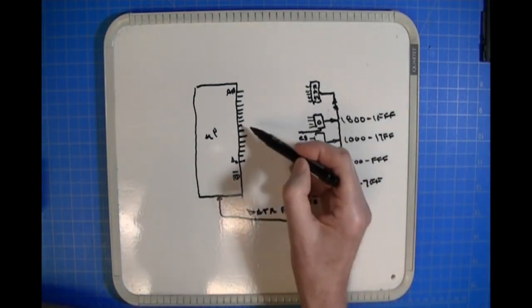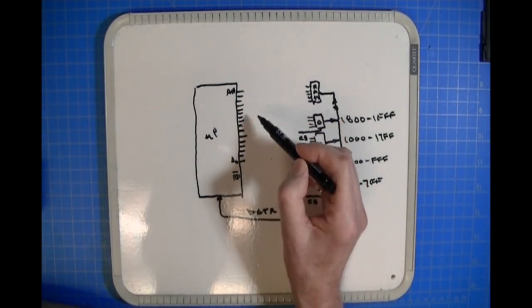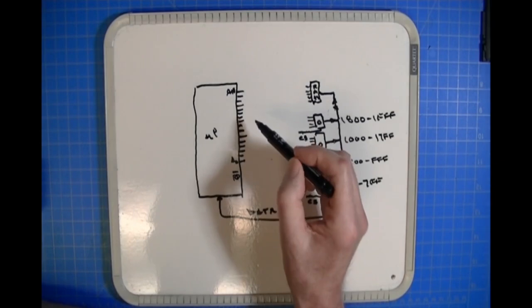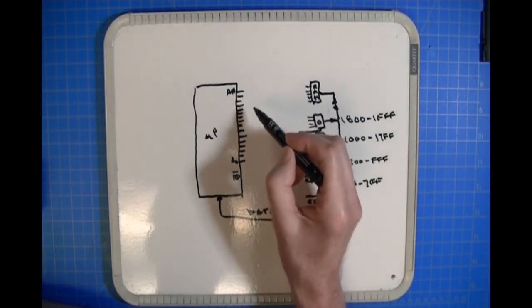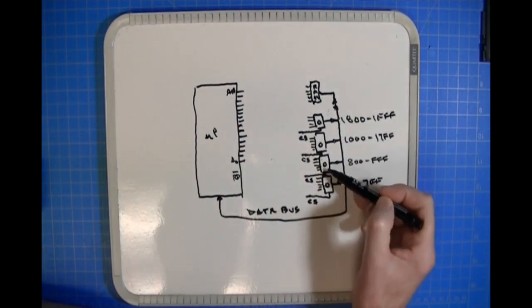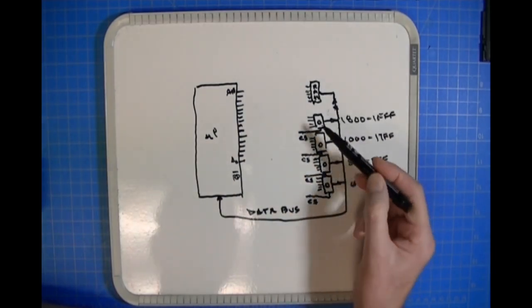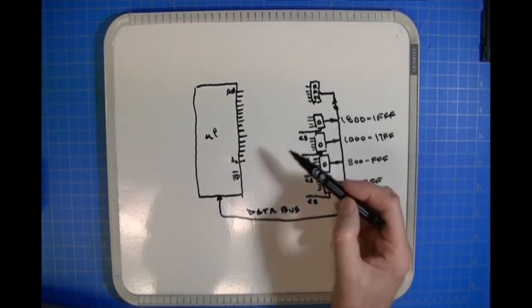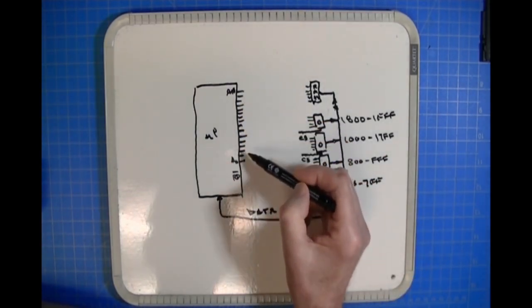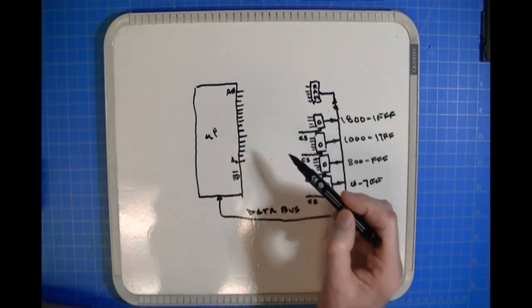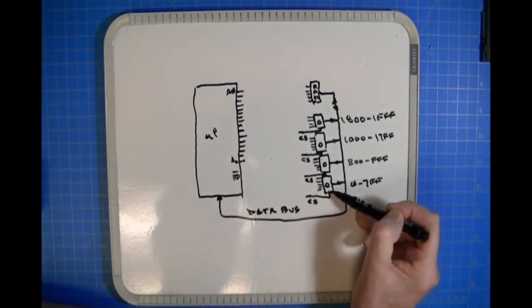But what about these lines up here? These lines are still going to be active, but even though they're active, they cannot allow the other three EPROMs to be accessed. So you want to, quote unquote, decode the ones and zeros on these lines so that only the first EPROM is going to be active.